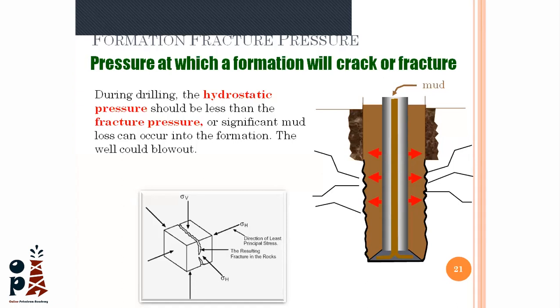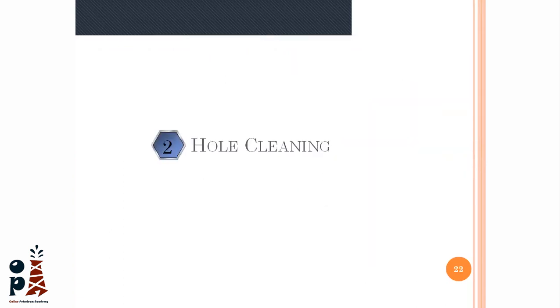So at this turning point, the formation starts to crack, and this is the LOT, the leak-off test. So this is how we calculate the formation pressure. Okay, guys, now we have already finished the first and most important function of a drilling fluid, which is pressure control.